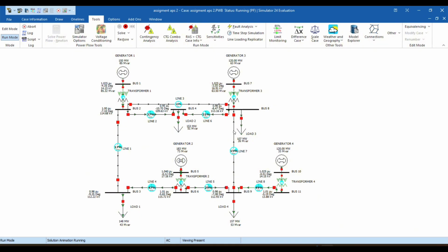Immediately we can see the change: the transmission lines now show the percentage load. For example, line 1 is 70% and line 7 is 15%. Also note the generator power output, the MVAR has been adjusted to meet system demand. Currently there are no red lines anywhere on the diagram, indicating that no components are overloaded. The system is healthy.